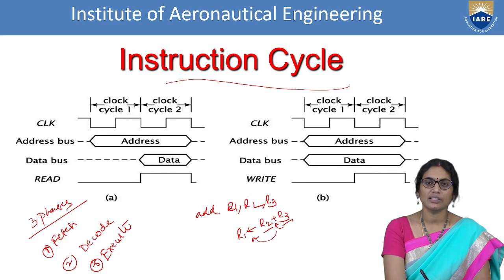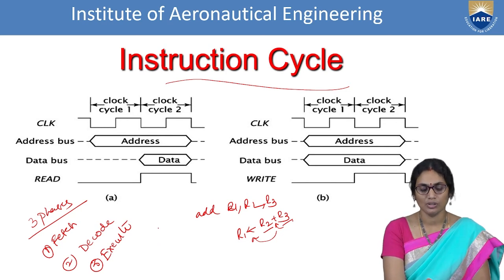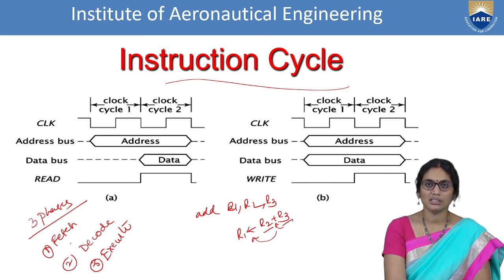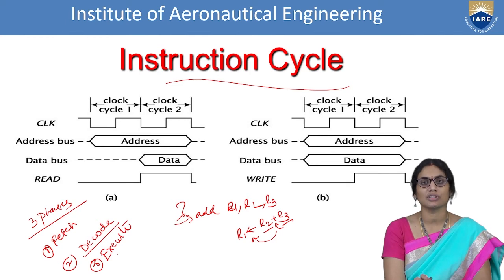First one is fetch, second one is decode, third one is execute. So fetch phase represents what the instruction is. So I have fetched the instruction. The instruction name is add R1, R2, R3. Now what is the second one? Decode. Decode means what does that instruction mean?